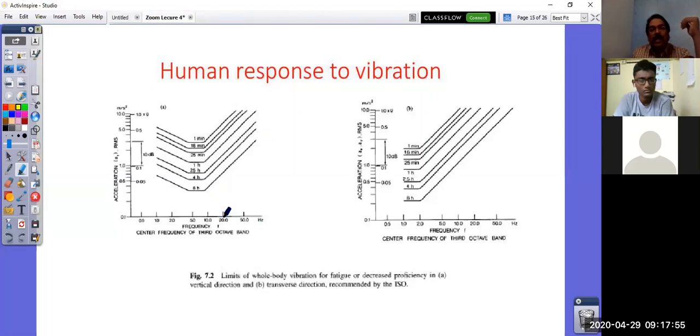So what I mean by that is, for vertical vibration at 20 hertz, suppose it can have a boundary value for 8-hour exposure, or 8 hours of test is done. This is a permissible amplitude. Whereas if you go for 10 hertz excitation to the vehicle, the permissible amplitude is this. So this is the range from here, this 5 to 10 hertz, where you have stable amplitude.